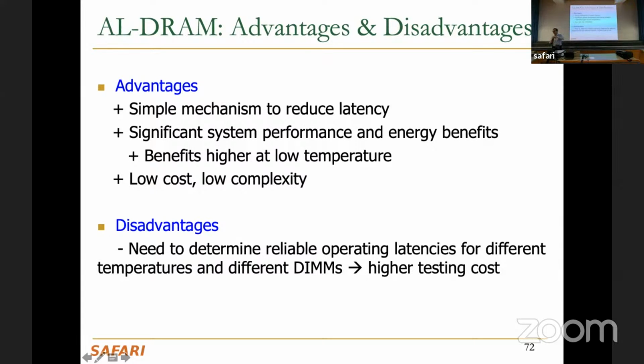Or time, or in the design phase, or after design in the manufacture phase? Well, this is after design. This is testing after design, because you need to look at the manufacturing variation and temperature dependence. It's costly in terms of, I mean, certainly manpower, yes, but it's really real time, because you manufactured, let's say, 1 billion chips, and you need to test all of them basically to figure out where they are, because everything has a different variation.